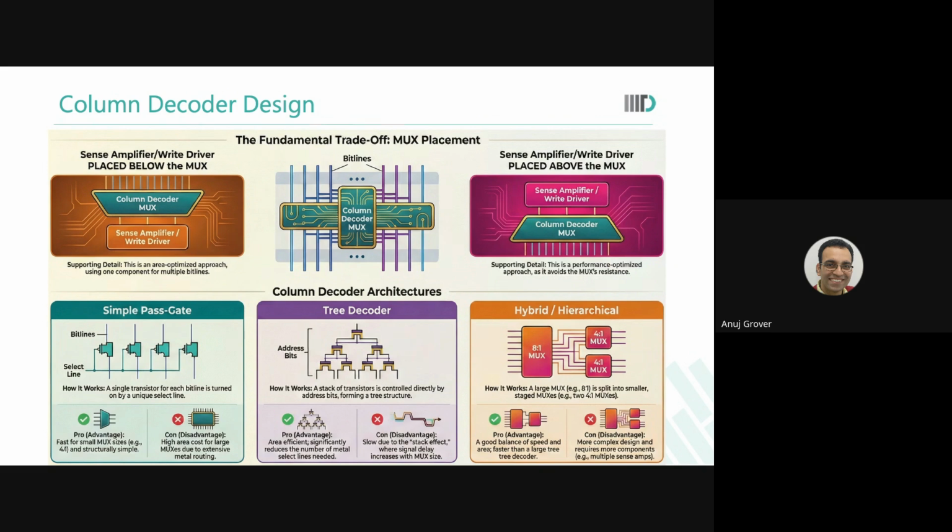So between this bit line and this bit line, BL of port A and BL of port B, there is a series of one pass gate that leads to the latch and the other pass gate that takes away from the latch. And then there becomes a short circuit path through these pass gates from the pre-charge of port A to the write driver of port B.